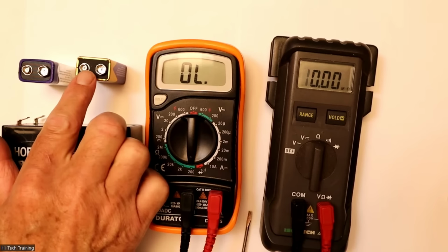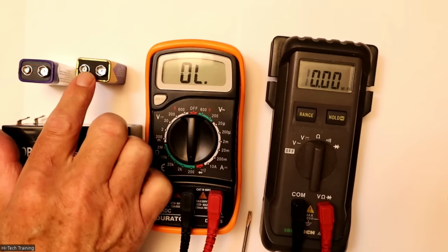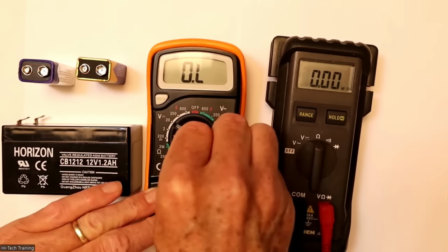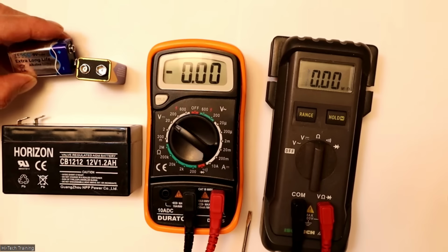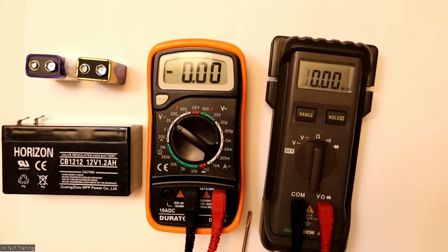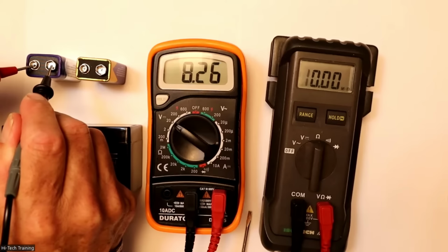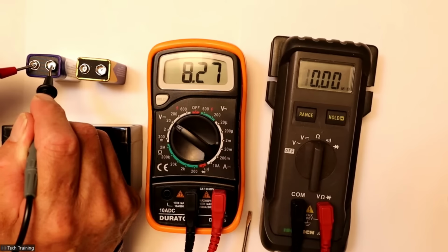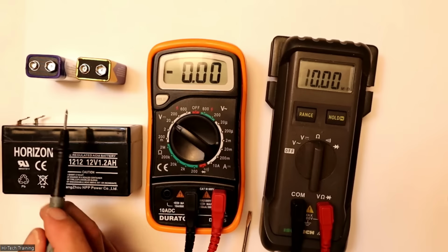Measure volts, so we measured this battery here, which was 9 point something volts. Let's go on to another one. Right, so this is another battery here, 9 volts again, but I'm not sure if this battery is quite as good as the first one we measured. And let's see what volts we're reading on this battery here. Oh, 8.27, so battery is not quite as good, okay? In fact, less than 9, so it's not that good at all.